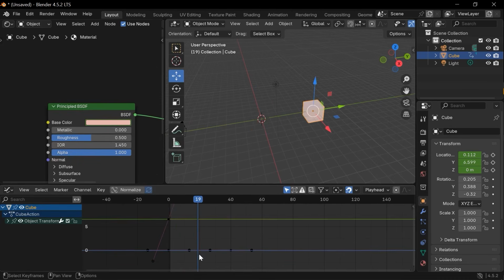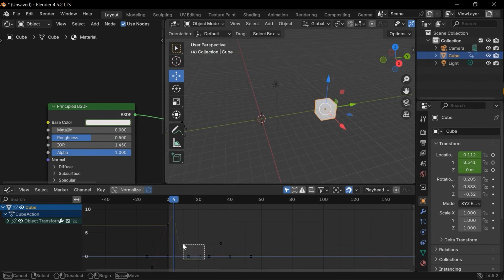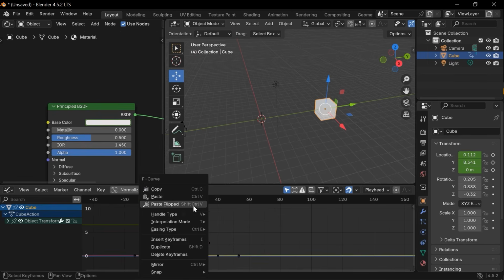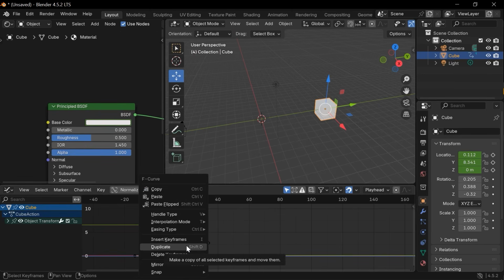And we can delete every keyframe, move the keyframes, and add keyframes using the auto key or I key. Also, we can apply group changes. For example, selecting all the nodes and right click. Here we have many options: mirroring the curve, duplicating the keyframes, deleting the keyframes. We can use the delete key on your keyboard or shift key for duplicating. You know about the I key already.